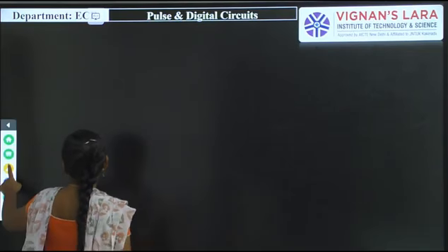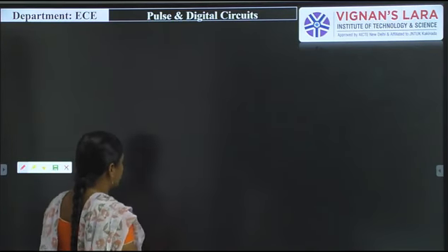The ECL logic family is used for designing which gate? Simply by using the ECL logic family we can design both NOR and OR gates. So this logic family is used for designing NOR and OR gates. Let us draw the diagram of this particular one. On the input side, it consists of three transistors. These three transistors form a